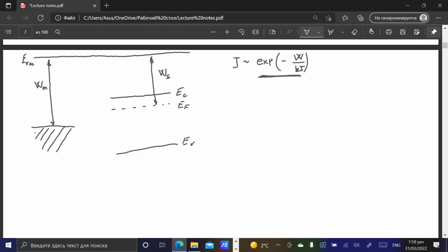According to the conservation of electric charge, if we build up some space charge in this metal layer next to the interface, it means that there should be some lack of electrons in the semiconductor. If we have some lack of electrons in the semiconductor, that should cause the presence of some uncompensated, positively charged donor centers in the crystalline lattice of the semiconductor.